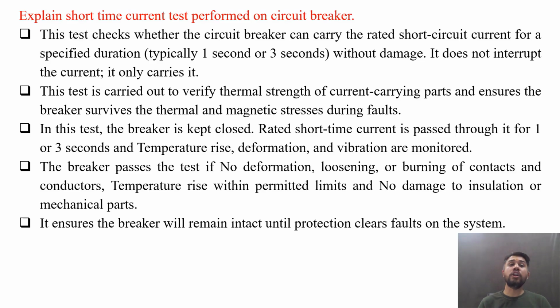Explain short time current test performed on circuit breaker. So this test checks whether the circuit breaker can carry the rated short circuit current for a specified duration, that is typically 1 second or 3 seconds, without damage.